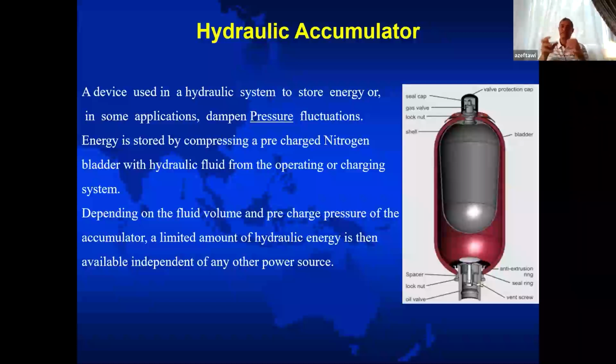It gives you 1500 psi, so you can activate your BOP, open and close rams, or apply more pressure to the injector to grip on the pipe so the pipe will not slip and run in the hole uncontrolled, or allow the well pressure to push it away. So this will give you more pressure to the injector. This is the idea and the function of the accumulator we have on the power pack.